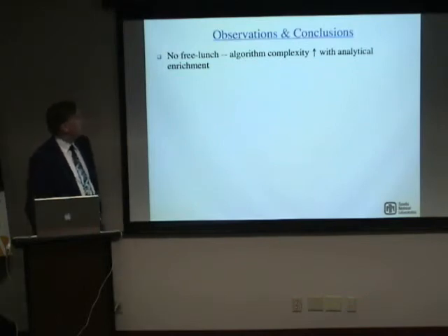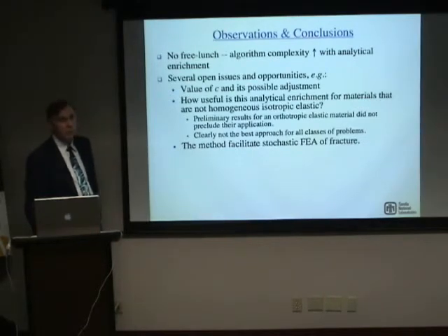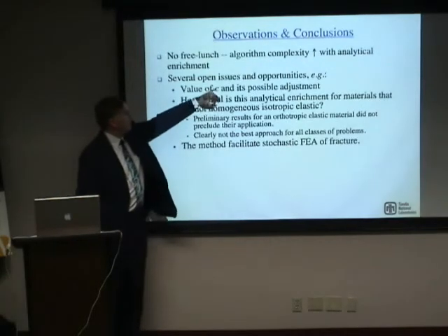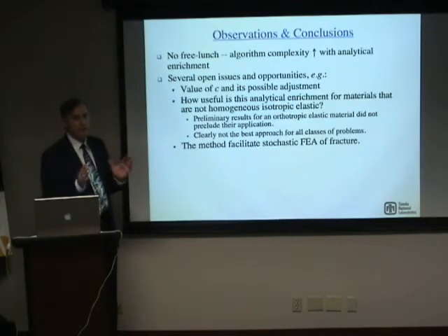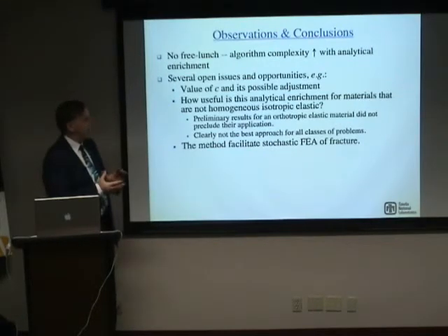I'll start with some of the negative, or well, they're negative but truthful, and that is there's no free lunch. The algorithm complexity certainly goes up when you bring in enrichment, especially analytical enrichment, which is more difficult than the Heaviside enrichment. There are several open issues, but also opportunities. I mentioned the fact that we find that C, not even being half the length of the actual cohesive crack, gives better results if it doesn't correspond to the actual length of the cohesive crack, and there are reasons for that when you're using just one term.